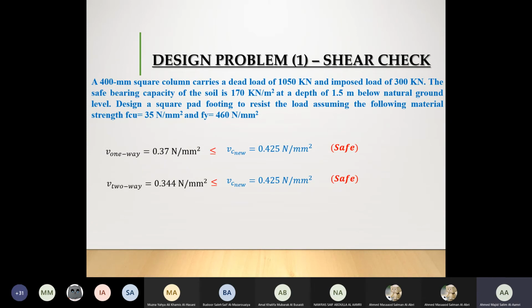Now, since I have explained it for the other section as well, normally if you have tried to solve many problems in the design of slabs, you will see that slabs are normally failing in deflection. Now, if your slab failed in deflection, what will you do? If you have started the problem, you reach to the end, and then it appears for you that your actual span by effective depth is more than the limit, means it fails. What will you do?